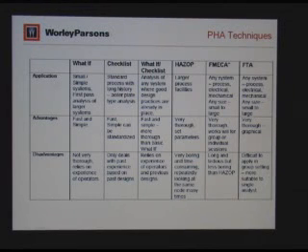also here it said it works well with groups or individual sessions. As a matter of fact, I never had to go through any FMEA technique with anyone else. Basically, you're the only one person who looks at it and produces this huge documentation, and other people review it. So to me, it's not a group effort. And the disadvantage is it's long, tedious. It says less boring than HAZOP, but I think it's about the same.